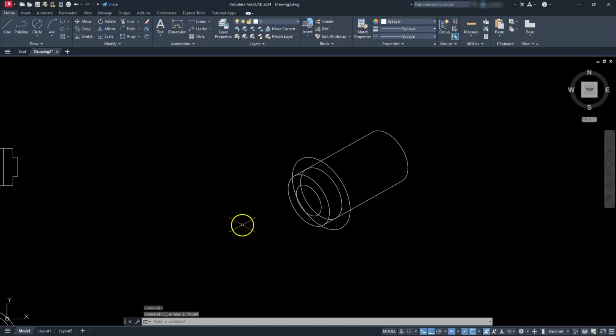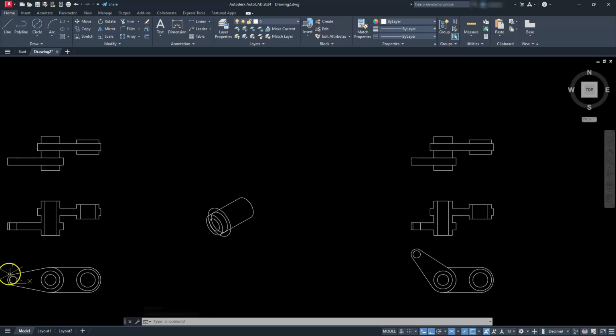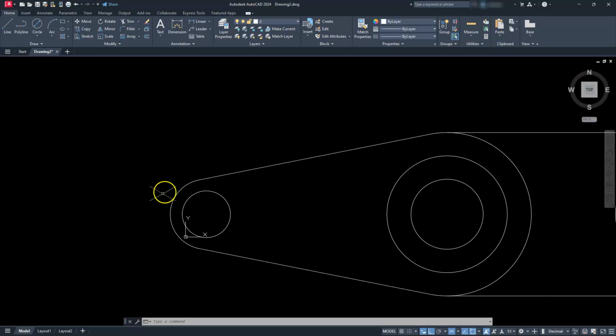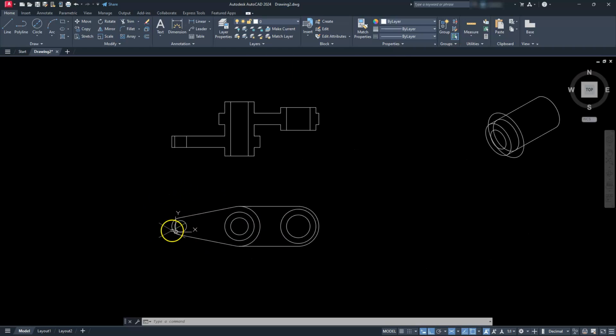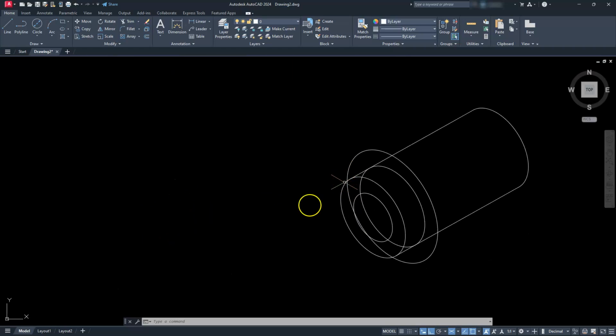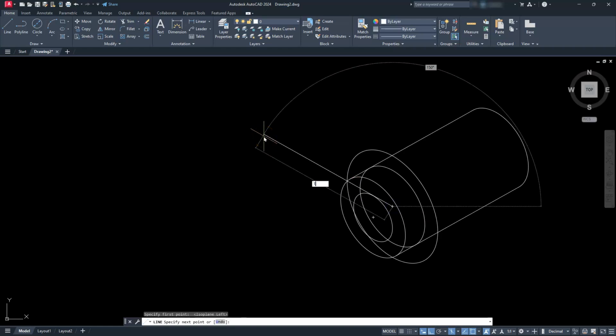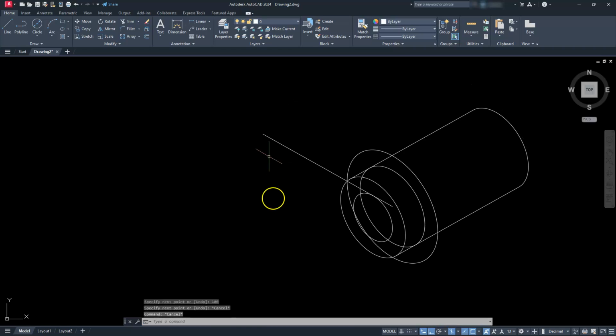And next we need to draw a circle that's located out here. So I'm going to create this part of my shape. So we're going to go ahead and draw a line, and I'll switch back to isometric left as well. And I'm going to find this center here. Do a left click here. Go out that direction a distance of 100. Let's go ahead and draw those two ellipses that are on there. So we have one that has a radius of 15 and the other one has a diameter of 20.